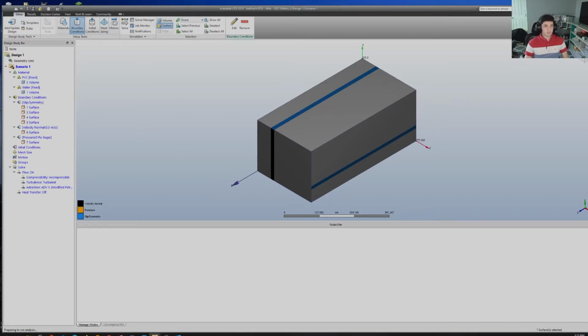This test is the most useful for improving the hydrodynamics of the body of the design because, as opposed to the second test, which is just propellers, the water is stationary, so you won't really see how water moves around your design. But with this test, it's like an actual wind tunnel test. Imagine you're holding a boat in the water and the water is moving around it. Whereas in the other test the water is still, but you're holding your boat in the water and the propellers are moving. If that makes sense.